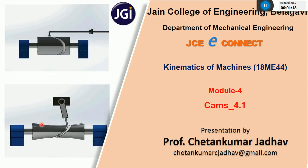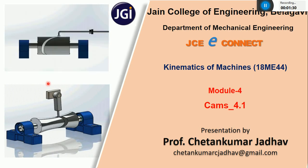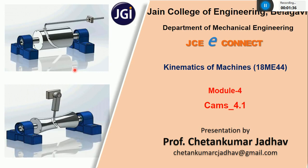Here also you can see this image. It is also an example of a cam and follower, but you can see the shape of the cam is concave, and it has one groove, and with respect to that groove there is an oscillating element, which is nothing but a follower. So in the first image the follower is reciprocating, and in the second image the follower is oscillating.